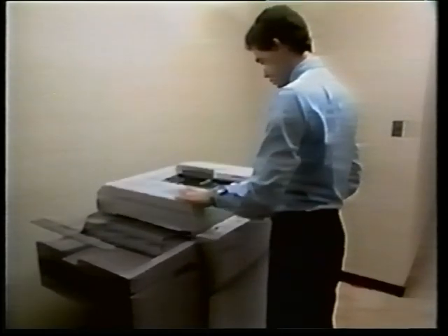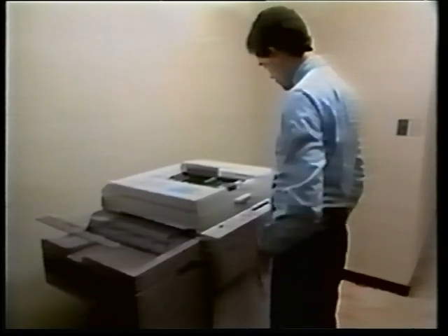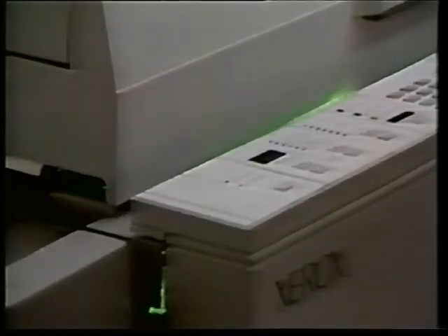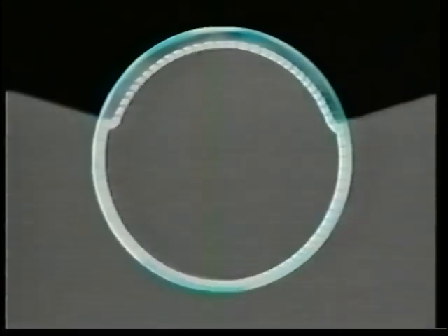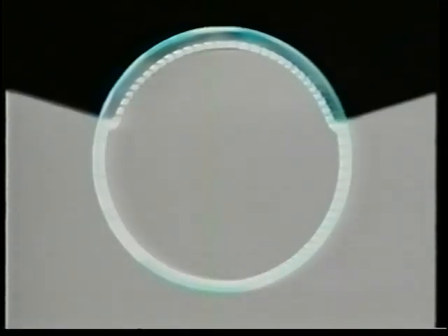Two very specialized fluorescent lamps, the reflector lamp and the aperture lamp, are used for many functions. The reflector lamp has a partial internal reflective coating, which provides directional control. Reflector lamps are useful where space is limited or in areas that are difficult to clean. The light is focused in one direction and eliminates the need for a separate reflector, which may become soiled.